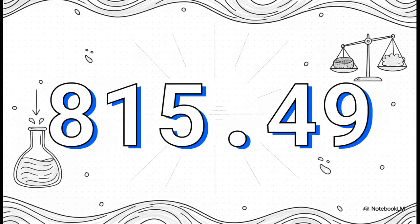Moving right along to step 3, we know specific weight equals density times gravity. So to isolate density, or rho, we take that 8,000 specific weight we just found and divide it by standard gravity, which is 9.81 meters per second squared. Doing the math, we successfully reveal the mass density of this oil to be exactly 815.49 kilograms per cubic meter.